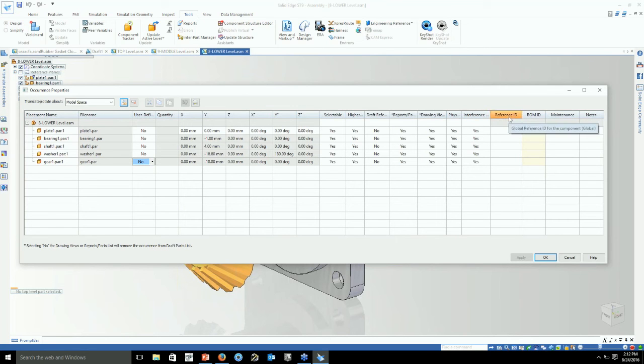When you set it up, you can set these for different types of change. So this is a global field. Anything right here would actually be set to the part. So wherever you change it, it would actually just change this one part file. And I'll show that as an example here shortly. This one is actually local. So this can only be changed after, you can't override it to be changed downstream. So it's only tied to the specific level that you created it at. And of course, this one's actually like a drop-down routine. So we have some maintenance things you can do.